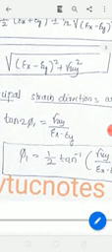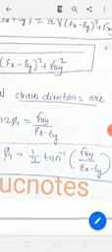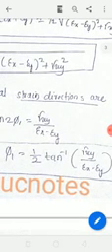The principal strain directions we can calculate by using this equation: tan 2 phi 1 equal to gamma xy divided by epsilon x minus epsilon y. So phi 1 I can write as 1 by 2 tan inverse gamma xy divided by epsilon x minus epsilon y. Like this you can use these available equations; no derivations are required, you only have to remember these derived equations, right?